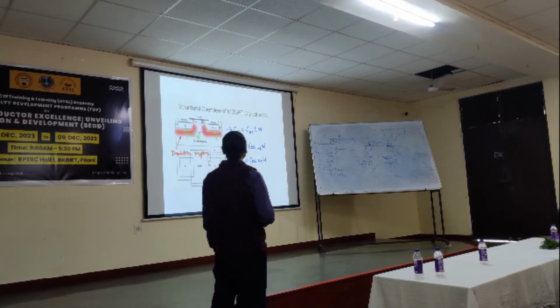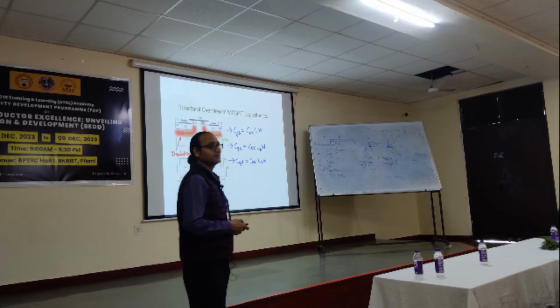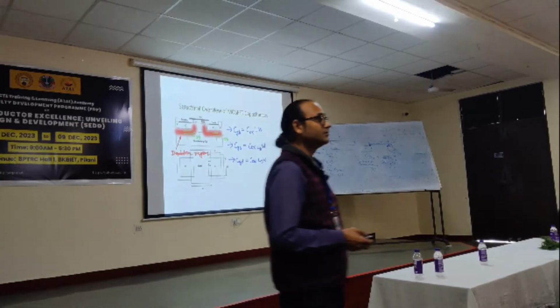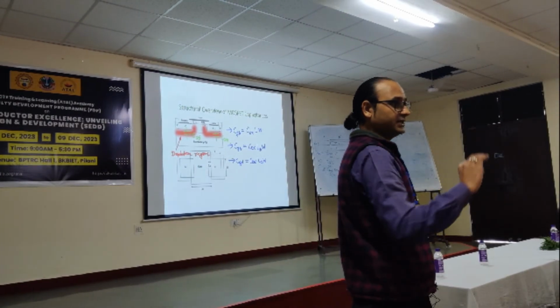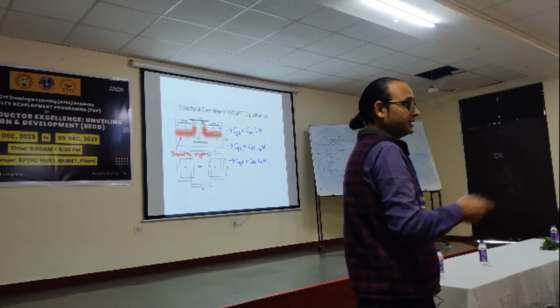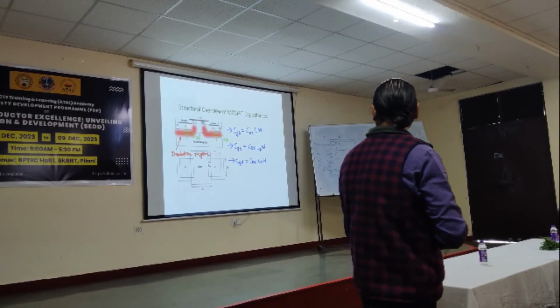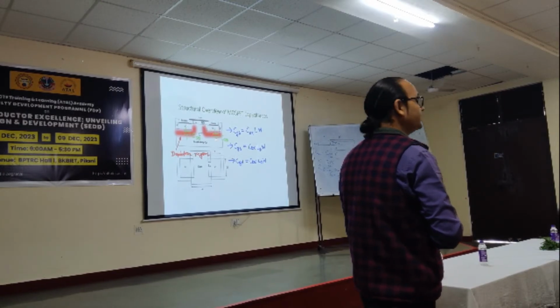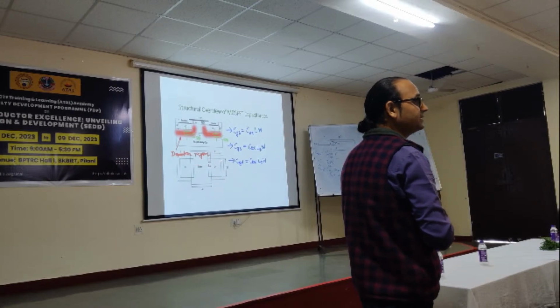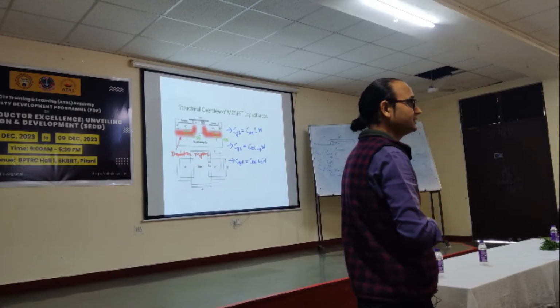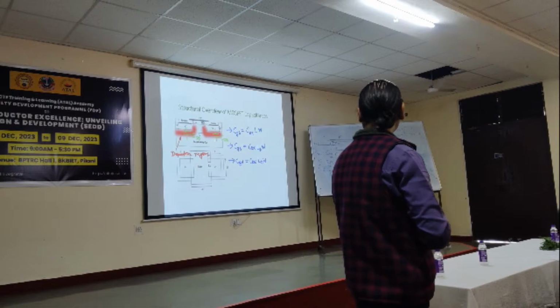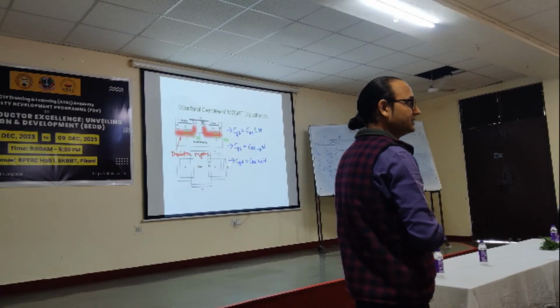And what is this now? Earlier that was the contribution of oxide capacitance from the gate. But see, this source is N type, the drain is N type, and this substrate is P type. There is one more capacitance. What is that? That is what we call depletion capacitance.